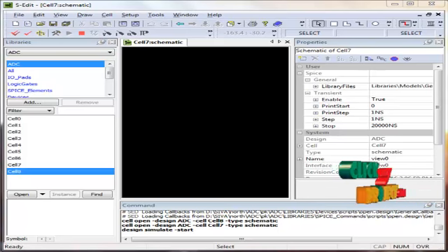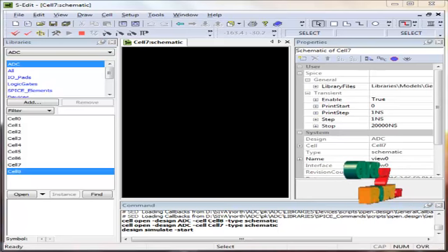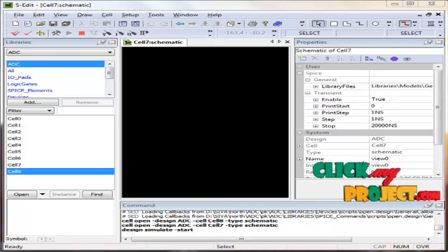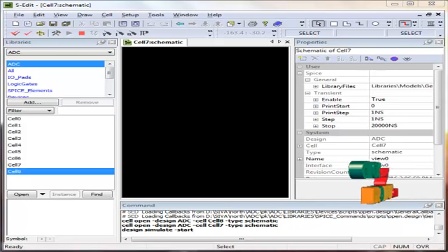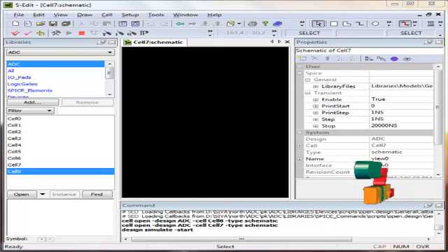If Vin is less than VDAC, the comparator output is a logic low and the MSB of the register clears to logic 0. The SAR logic then moves to the next bit down, forces that bit high, and does another comparison. The sequence continues all the way down to the LSB. Once this is done, the conversion is complete and the n-bit digital word is available in the SAR's code register.